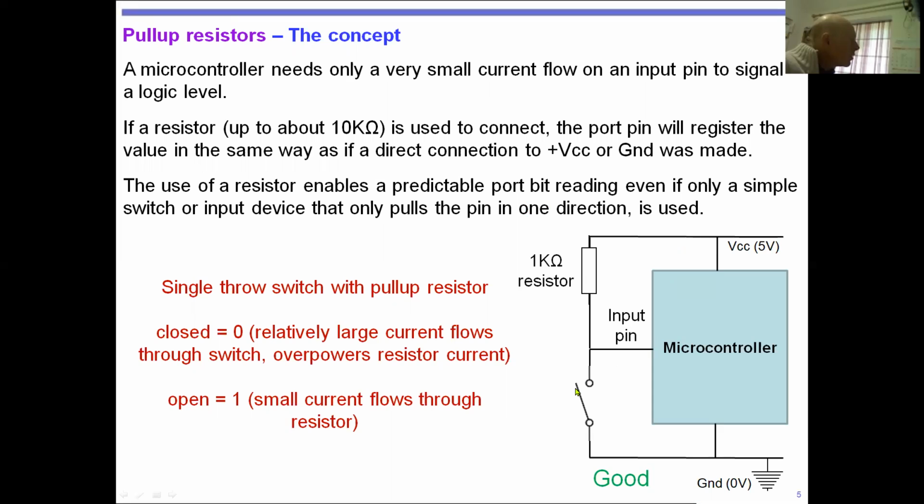But when this is shut, because we have this resistor, we are not damaging the supply, and we're not draining the supply so quickly. We are still actually draining the supply, but not so quickly, and not enough that the voltage will drop and this will reboot. So it's much better in all respects. But you see, this needs extra components, extra wiring, extra cost. It's not desirable to keep putting in extra bits.